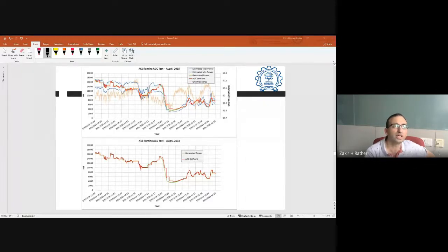For example, in Ireland, back in 2011, the maximum penetration of wind and solar power was restricted to 50%. You could not go beyond that because you have stability constraints. Now they had to curtail wind power primarily beyond 50%. So if your plant, solar PV or wind, is already being curtailed because of, let's say, other reasons, you already have to operate it at non-MPP.